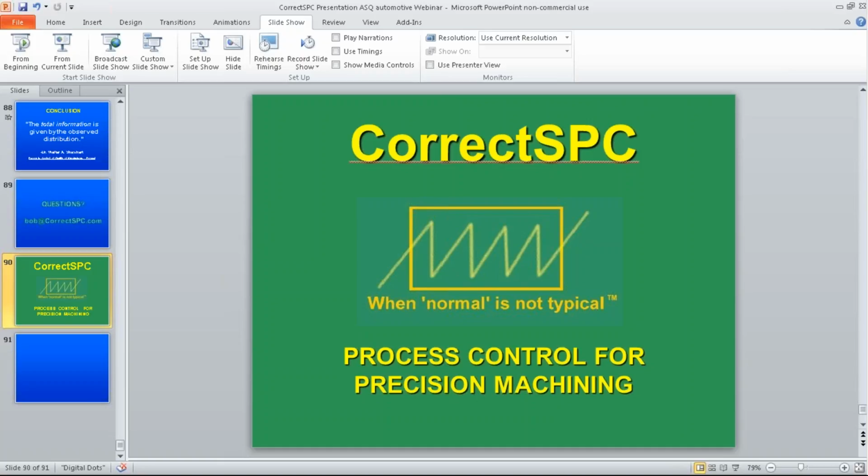As long as your data falls within the control limits, you've met that. That is your goal. And there may be some exceptions where an individual didn't catch it in time, or a tool broke. But as we know, those are special causes, and you adjust for that, and you usually don't include them anyway. So the long-term process capability is the control limits in comparison to the spec. That's it. There's really nothing else. And that goes back to the calculations for the continuous uniform distribution.